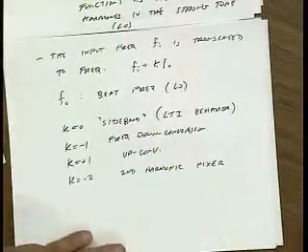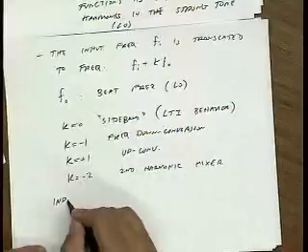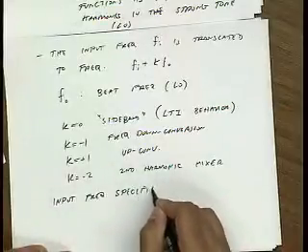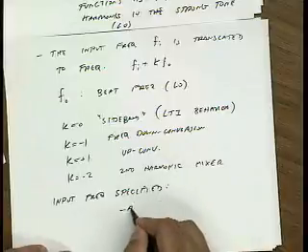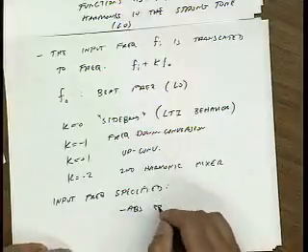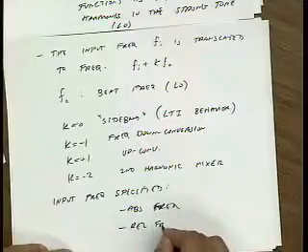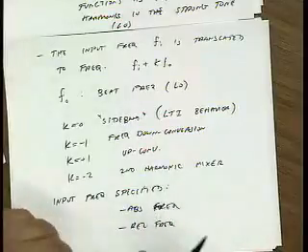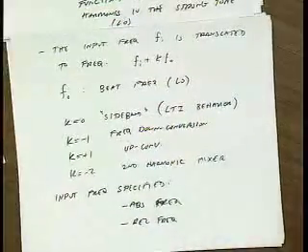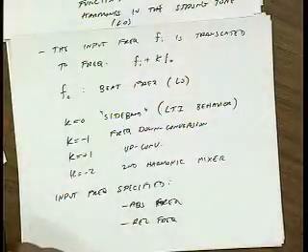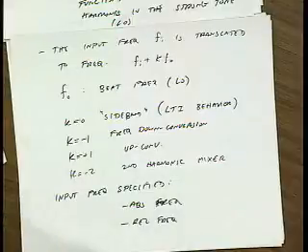So there's one interesting thing: you specify the input frequency as either an absolute frequency or a relative frequency, where you would specify it relative to the beat frequency. So I could say 100 kilohertz away from the beat frequency, or a megahertz away from the beat frequency. Or I could say it's 1.1 gigahertz explicitly, for instance. Okay?